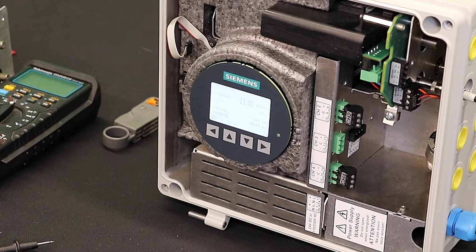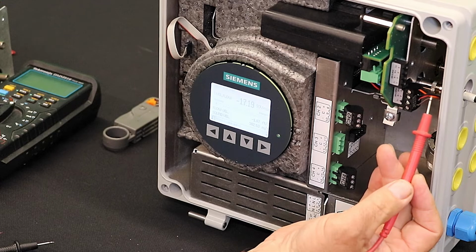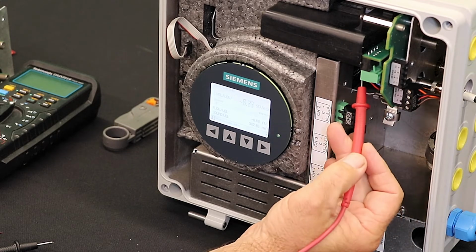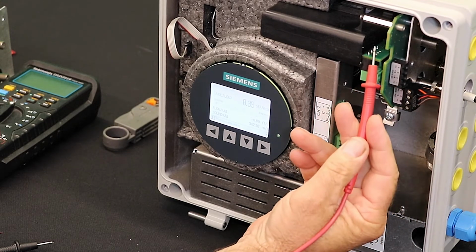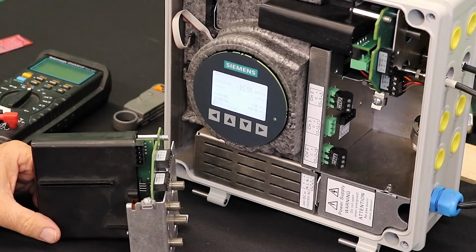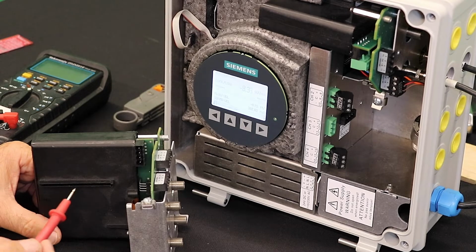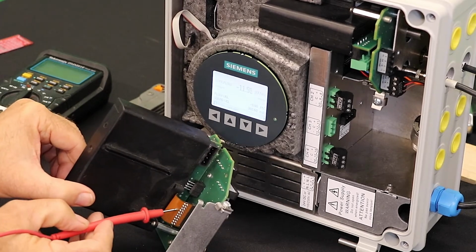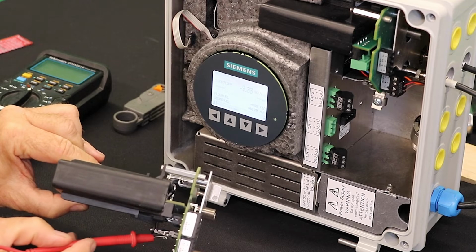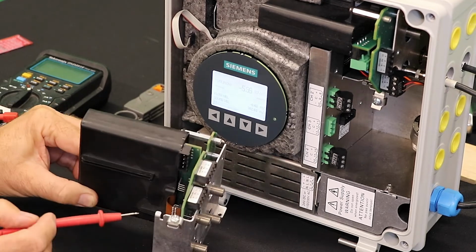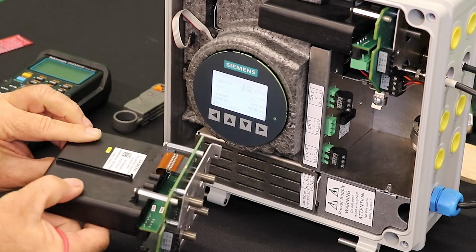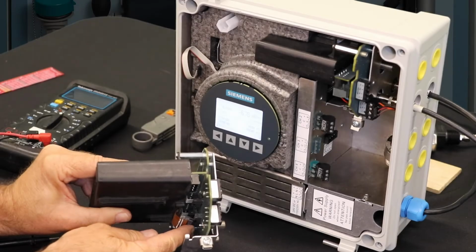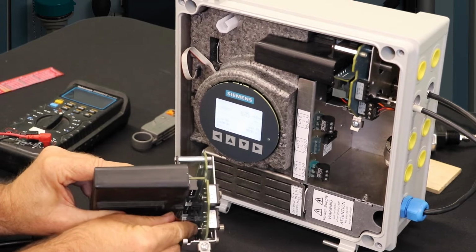The other possibility is on the other side of the board where the coaxial cables come in, there's a connector for path 1 and a connector for path 2. I've taken the digital sensor link, or DSL, out of another unit to show you, but there's this ribbon cable with a connector that has the potential of becoming loose. This would be the one for path 1. This would be the one for path 2. This can go and get plugged back in.